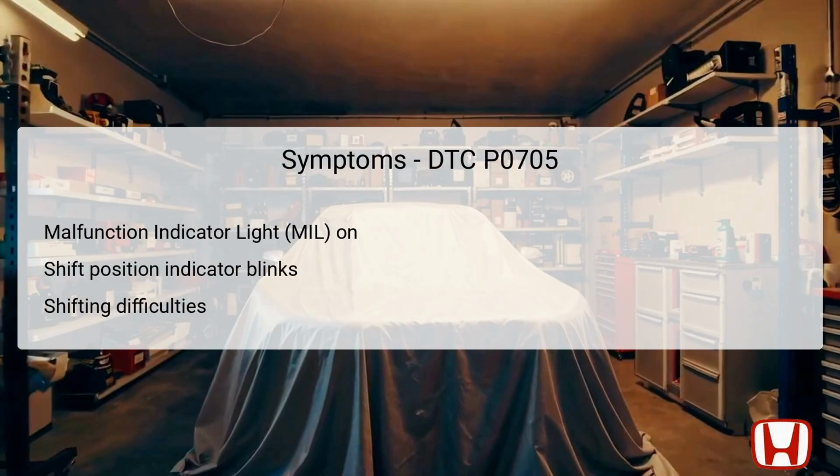Moreover, drivers may experience actual shifting difficulties, such as reluctance to shift into certain gears, or the inability to properly engage park, reverse, or drive. These symptoms collectively warn the driver of an underlying mechanical or electrical issue within the transmission range switch system. Ignoring these signs may lead to more severe transmission issues, emphasizing the importance of immediate diagnostics.